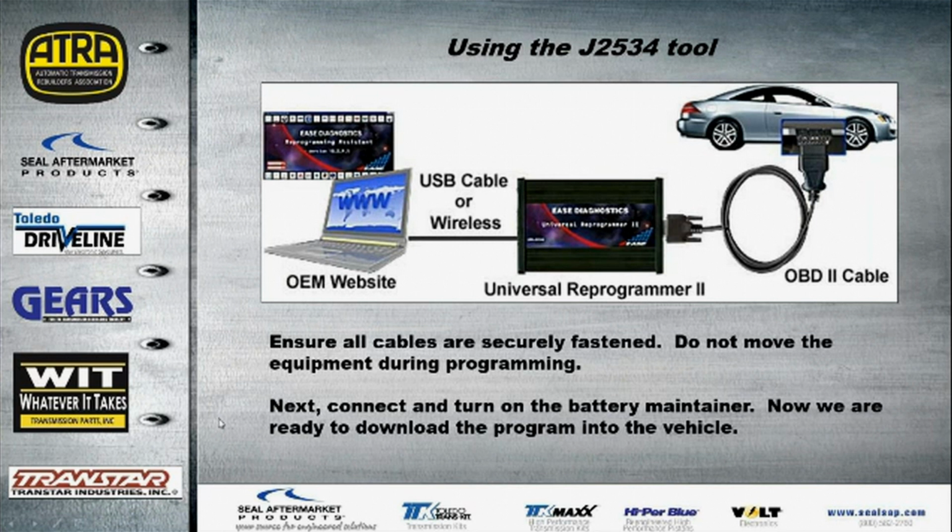Next, you want to connect the battery maintainer and turn it on, and get that set for the proper voltage. Again, the proper voltage is going to be indicated by the OEM in the instructions. So there's a lot of reading that you have to do before we actually get to this level, just to make sure that we don't miss anything.